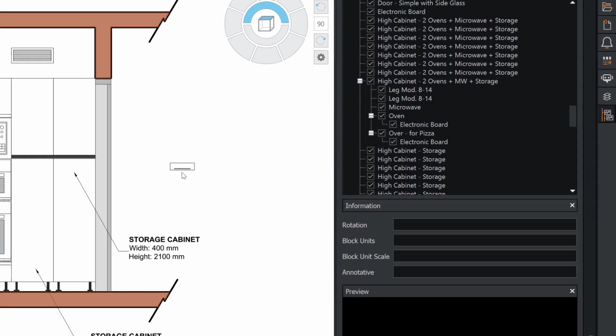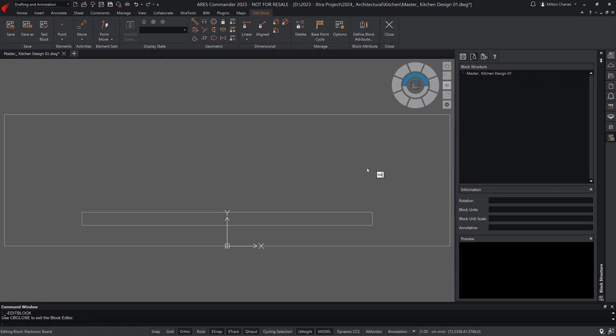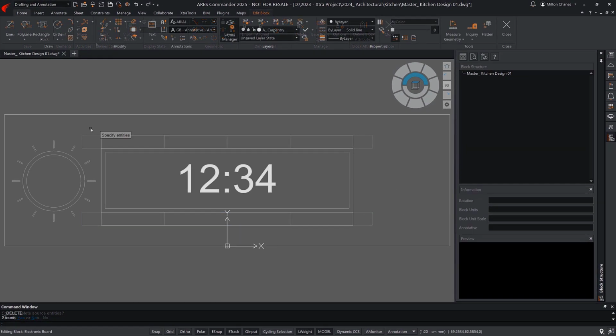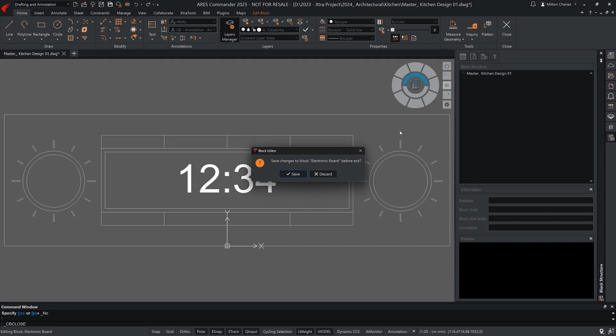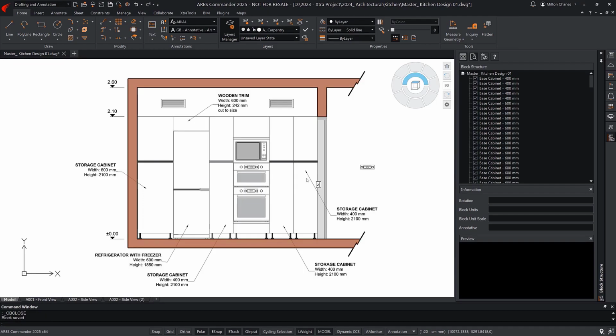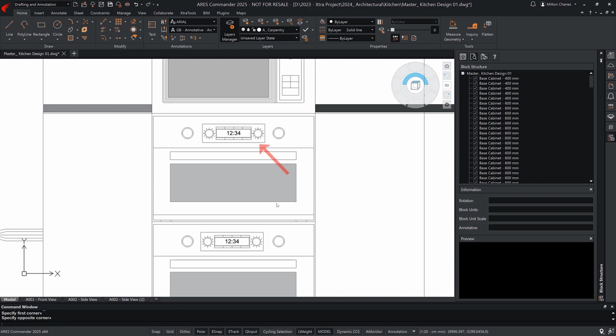It should be noted that the block we just inserted is the same as the nested one, it's just used differently. Now we can edit it as desired. And when we save the changes, we are modifying the definition of this block and all its instances, regardless of where they are being used. Therefore, we see the nested block updated.